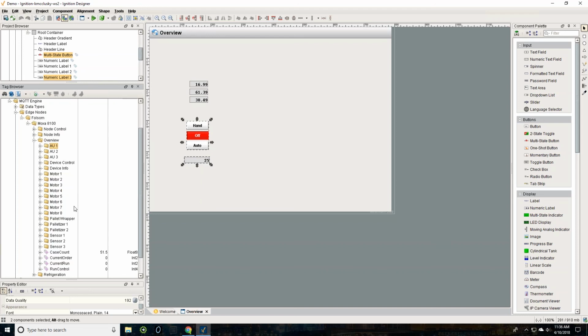The MQTT protocol also makes it so that these pieces of information that I have streaming back here, each one of these different tags, this is super lightweight. So this HOA tag, for example, that has a 0 right now, this is not sending anything over the network. This is just quiet. This is only sending things as they change, and it's sending it in a compressed format.